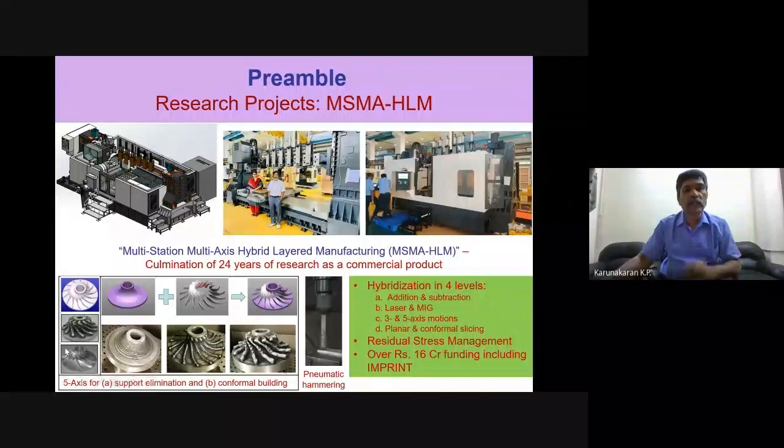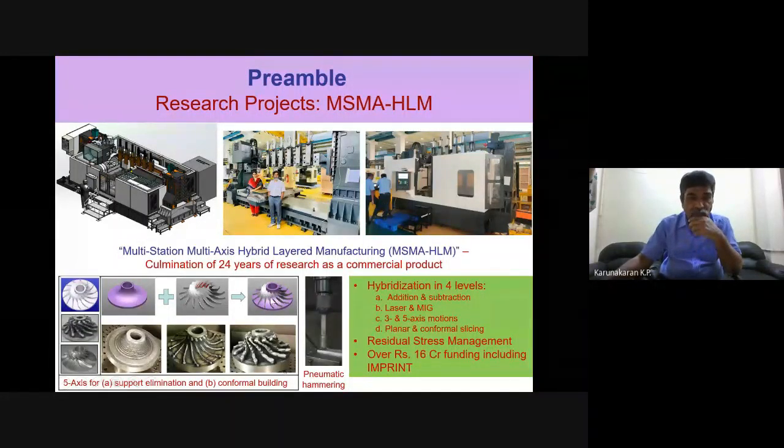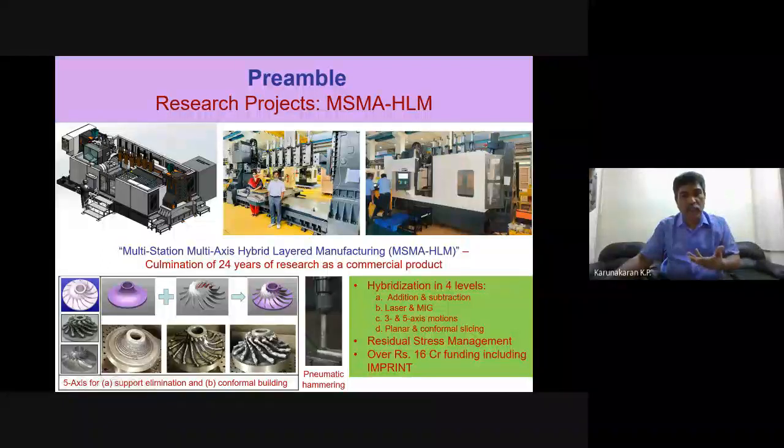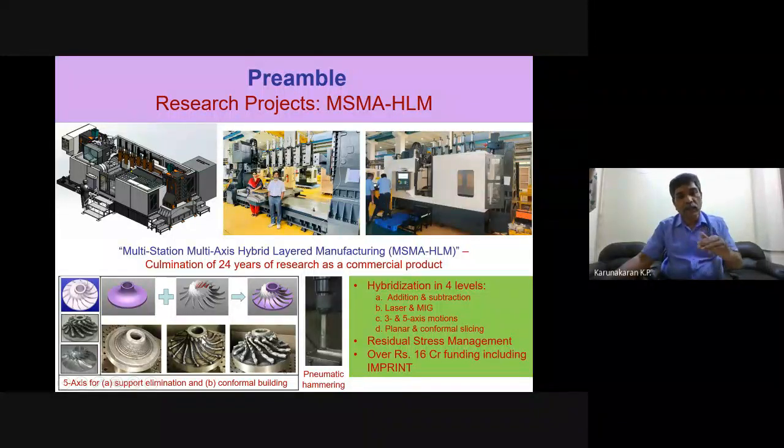So this is traditional additive manufacturing. Subsequently, we thought we can divide this impeller geometry into the hub and blade. As you can see, the hub is a simpler geometry which can be built on a 3-axis machine. So that's what we did. The hub was produced on a 3-axis machine, and the blades were added in 5-axis motion on top of this. So you see that it's no longer horizontal growth. The way all natural or biological systems grow, we start from chromosomes, and then we grow in layers, but these layers are no longer horizontal layers, they are conformal layers. That's where I'm talking about planar layers and conformal layers. So in this particular case, we could go up to conformal layers, very close to nature.